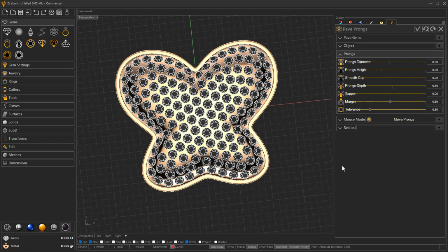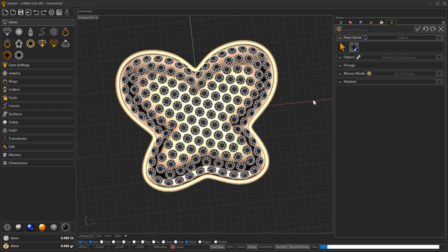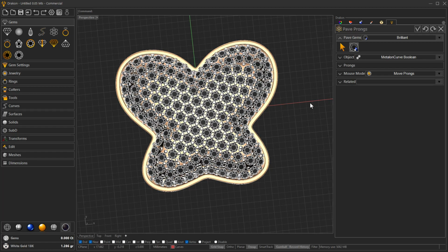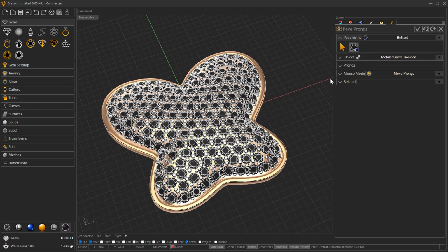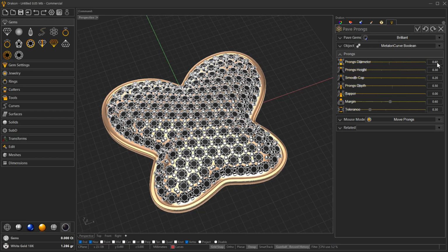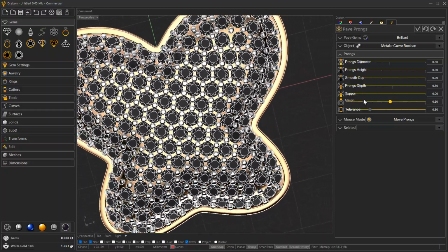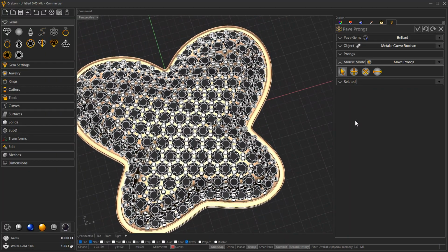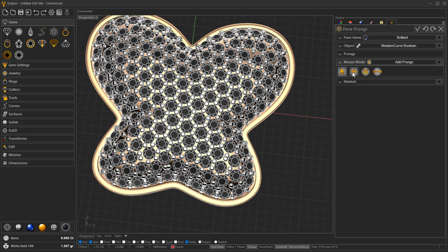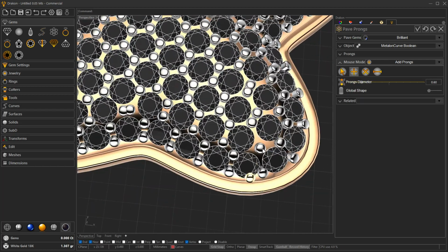the prongs. So I just need to select the group of gems, and now we will readjust here, for instance, prong size. We can define all the measurements as well as control manually. There will be a couple of them that you'll see most part of them are properly placed. We can adjust the margin, but there will be always one or more positions that we can readjust.